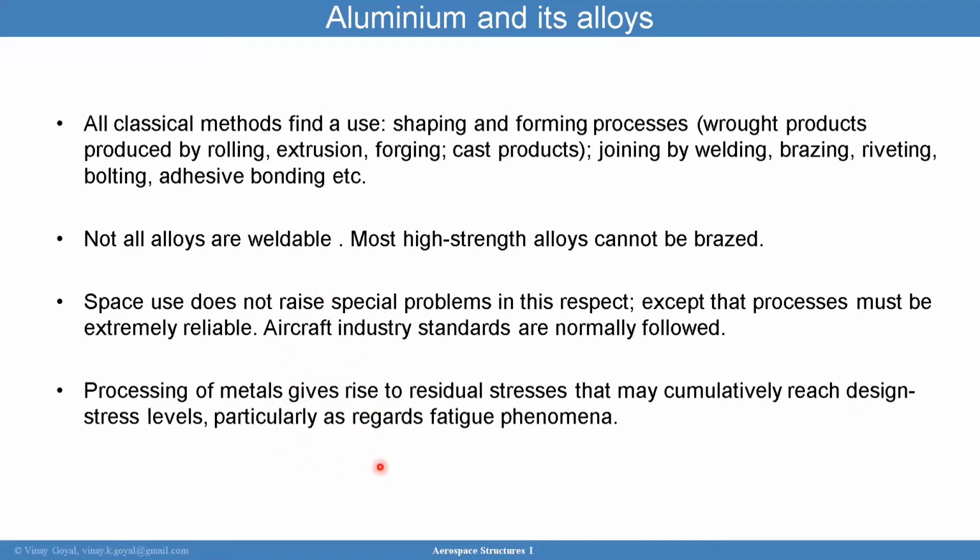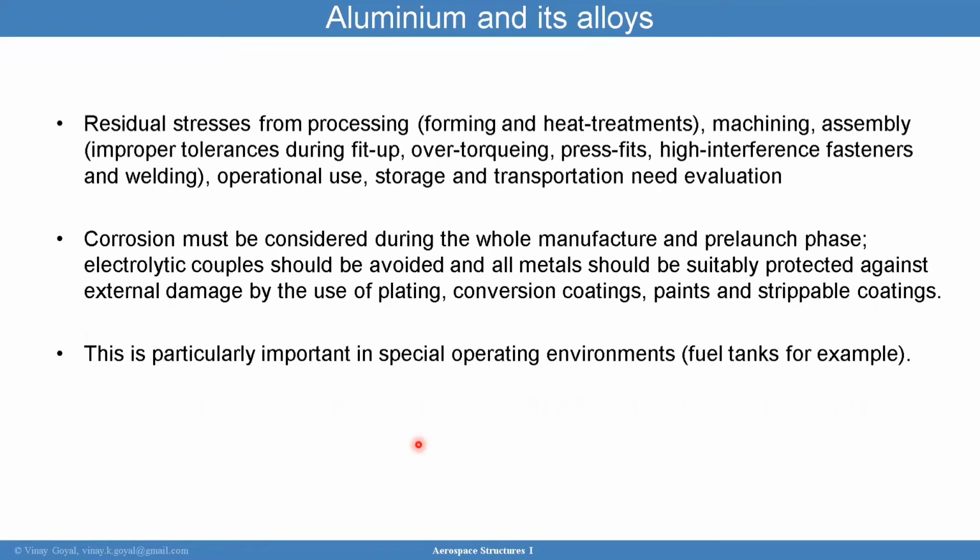The processing of metals will give rise to residual stresses, which need to be considered, particularly when you're looking at fatigue phenomena. Residual stresses from forming processes can be a problem, and they can cause issues like machining issues and assembly issues like fit-up tolerances, and the storage and transportation need to be looked at carefully.